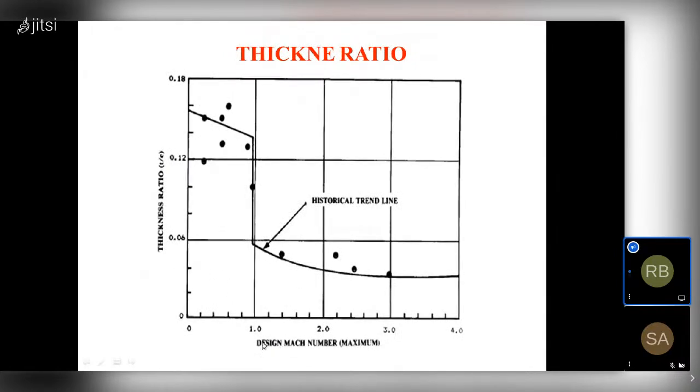Mach number, right? So we have two Mach numbers. For this Mach 2, which means if you are designing an aircraft which has to run with a velocity of Mach 2, then for that case you have to select the aerofoil having a thickness to chord ratio of 0.05.